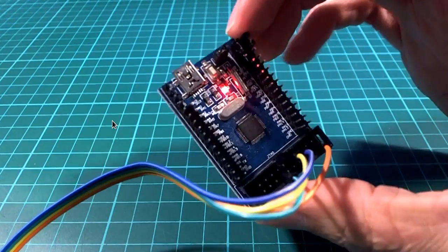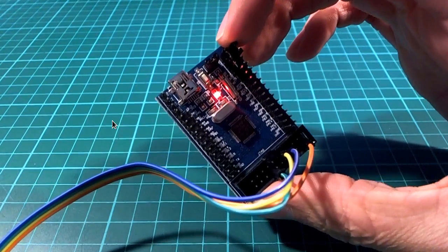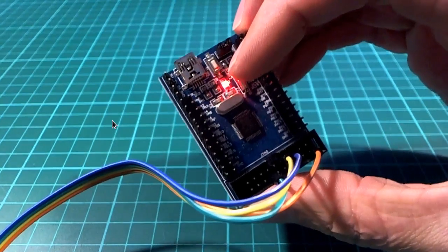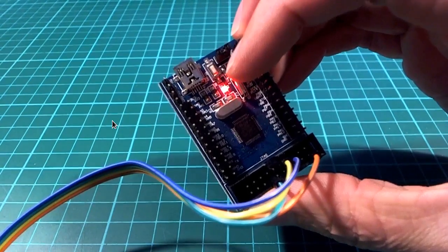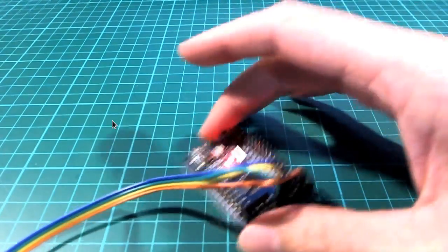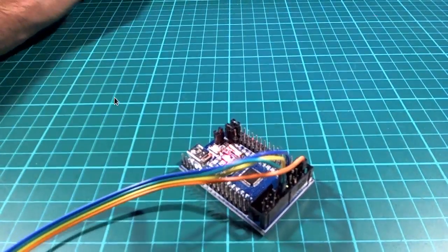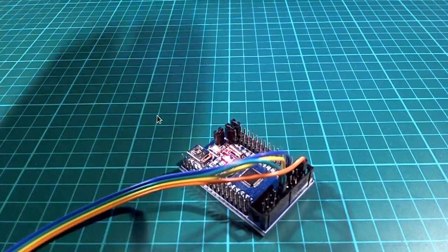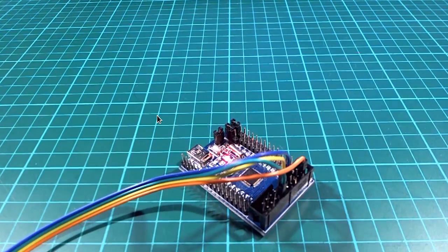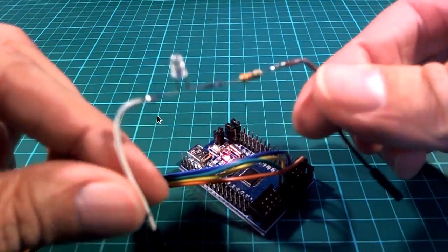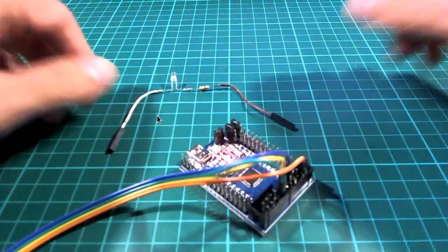Okay, so now we should have a blink program running on there, but there's nothing to look at because that LED there is just a power LED. It doesn't show you anything more than the fact that there's power onto the board. So we're going to have to connect up an LED, and I actually just used my voltmeter for this to check it the first time, but since I'm making a video for people to look at, I set up a little LED like that we can check it with.